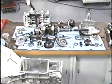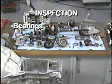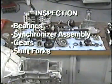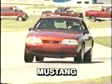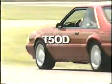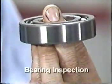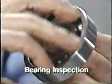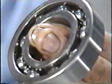If an inspection is necessary, the major components that should be checked are bearings, synchronizer assemblies, gears, shift forks, and the transmission case. In the following examples of inspection procedures, the T50D transmission used in Mustangs will be inspected. Begin by inspecting the bearings. Clean and lube the bearing, then spin the outer ring by hand. If roughness or vibration is noticeable, the bearing should be replaced.